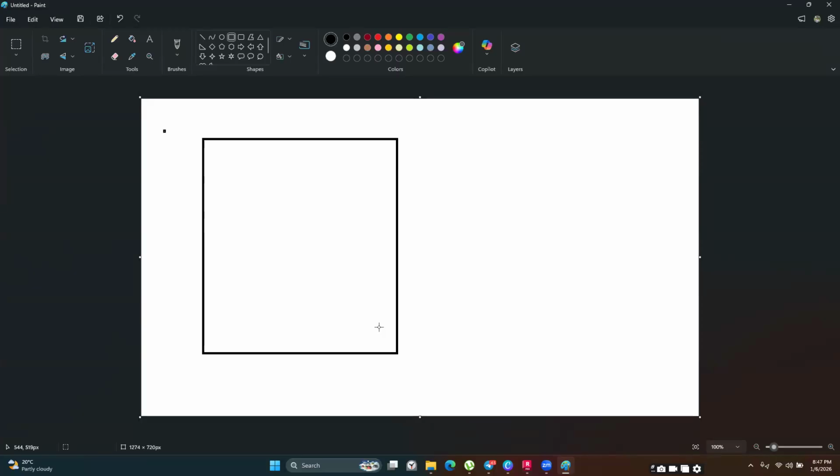The reason is the local axis. For the slab, the first line that you model is going to be your X, and then the second direction is going to be your Y in the local axis.